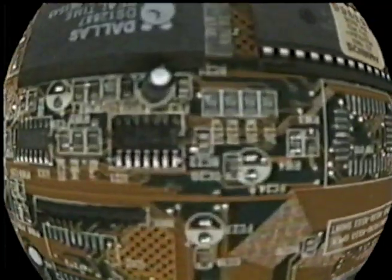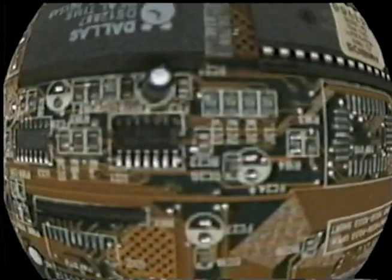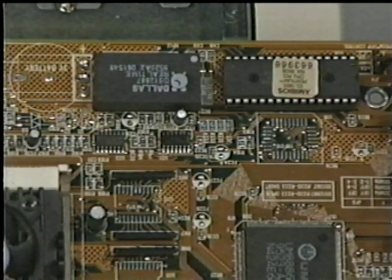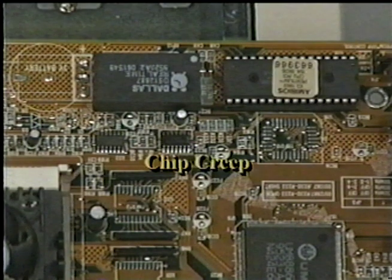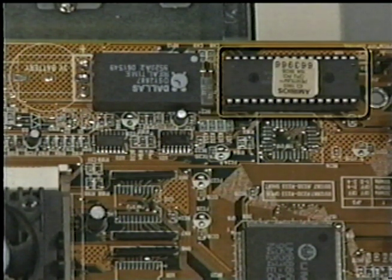As our system heats and cools, it expands and contracts, and this physical expansion and contraction causes components that are plugged into sockets to gradually work their way out of the sockets. This is chip creep. On our board, the only socketed chip is the BIOS, but you may have more on your motherboard.